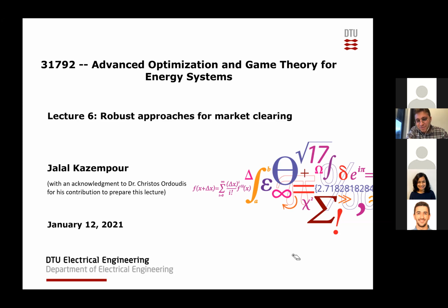While in scenarios 2, 3, and 4, we always have wind power excess. So in all of them, G2, as our flexible unit, needs to provide down regulation, while G1 is unchanged because it's fully inflexible. The demand is not curtailed because load curtailment is a costly resource.